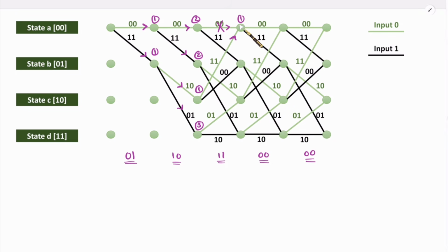And this weightage 1 is with respect to this link. So you will have to eliminate higher weightage. The reason is higher weightage comes with higher Hamming distance, right? Similarly, at this node, a node with weightage 2 is connected. If you follow this path, here we have 1, 1, here we have 1, 1. So 1, 1 and 1, 1 difference is 0. So weightage over here will be 2.